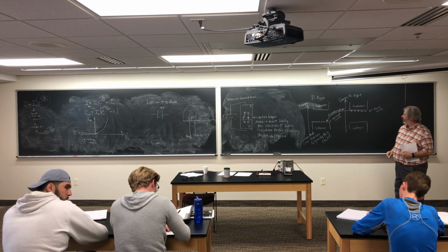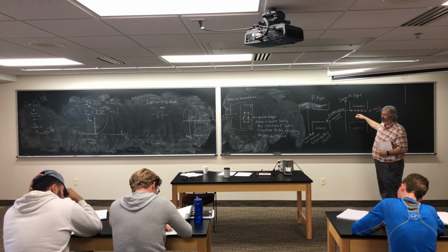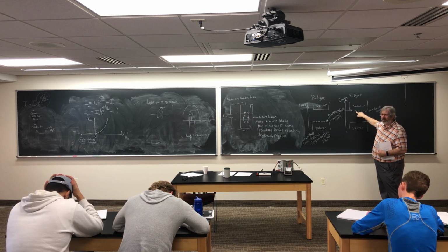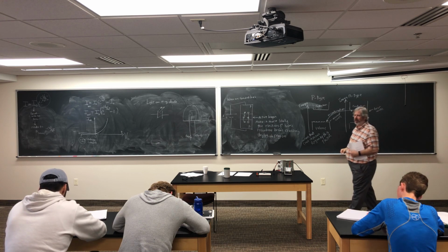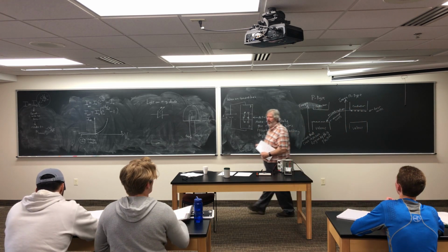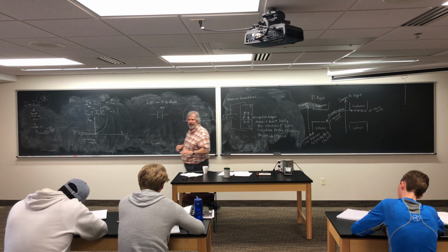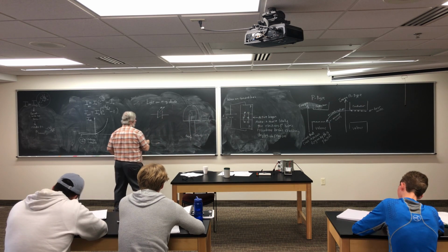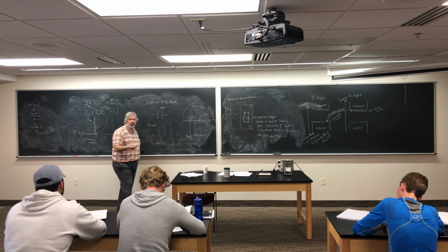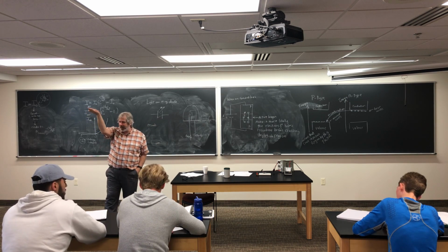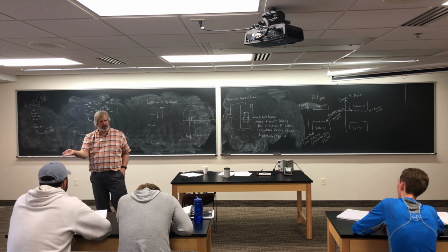So there's an energy difference here. It's basically the energy difference of the band gap, because these levels are right below the conduction band and these are right above the valence band. So the recombination energy is roughly the band gap energy. Okay. So the electrons lose that energy. They were up there by the conduction band, and they've moved down to a lower energy level. Okay.